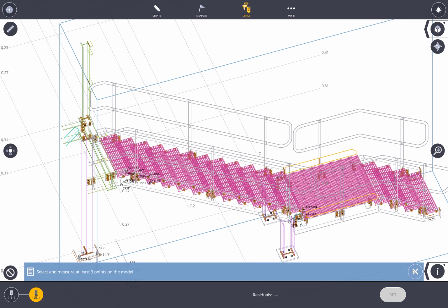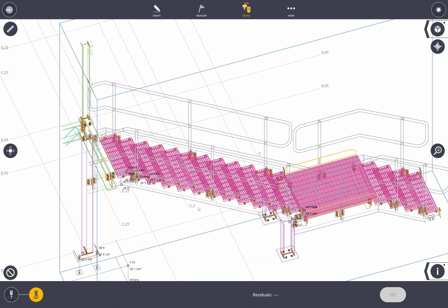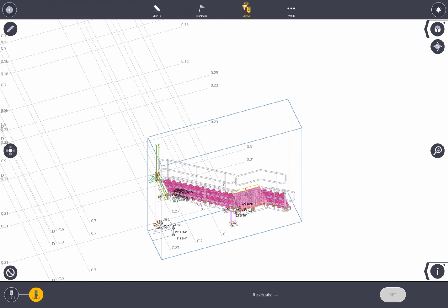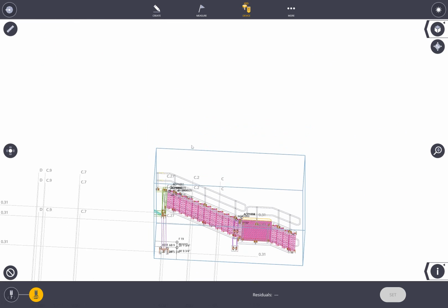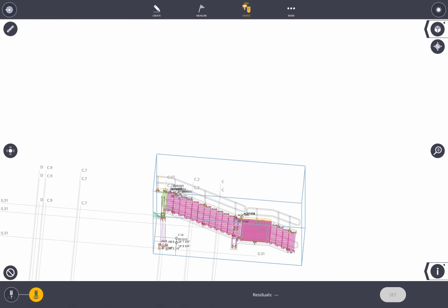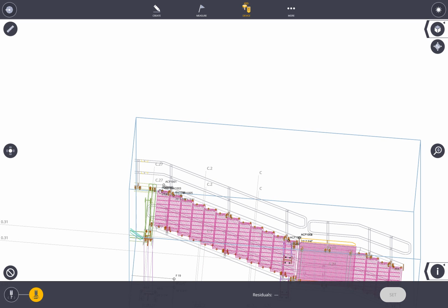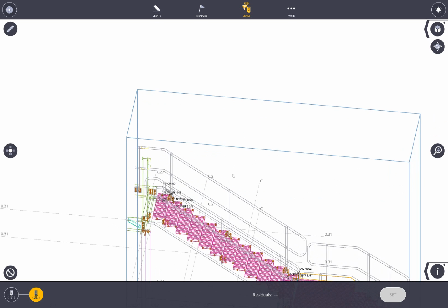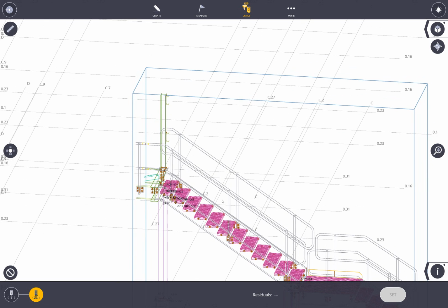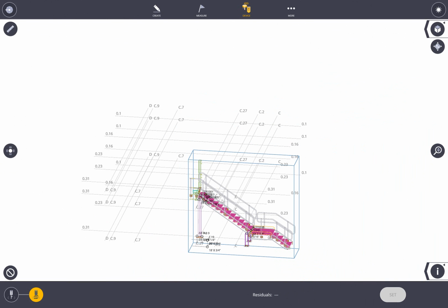So it's a little tough to fake that out on the emulator, but basically if we shot those 3 control points, the instrument would now consider that this position is laying down and that we're looking at the bottom of the stairs. We shot those 3 points, and now we could start to lay out all the bolt holes and any other points we had created during that data prep operation. So a really convenient tool for doing shop layout or assembly out on site, or tilt-up panels or prefab items out in the field as well.